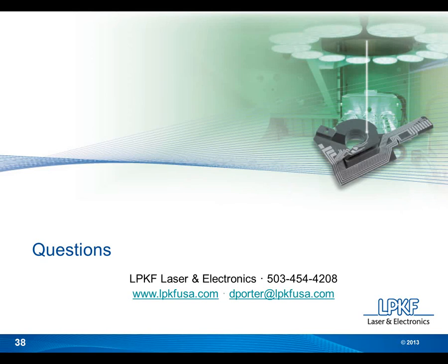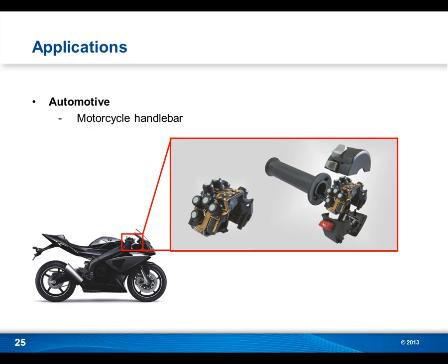So I have another question. This one comes from John. What is the surface mount compatibility with complex 3D structures such as the motorcycle handle? Does this need additional equipment? Yeah. There's a few manufacturers that manufacture 3D SMT equipment. Now it's very specific to the 3D world, and a lot of times it's custom made to an application. It's a little bit more complicated to set up and program than your typical SMT pick and place equipment, but generally works in the same way. Gotcha. Thanks, Don.